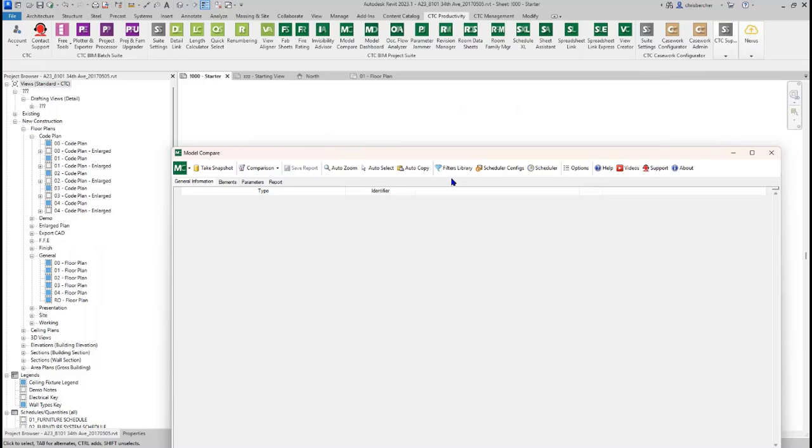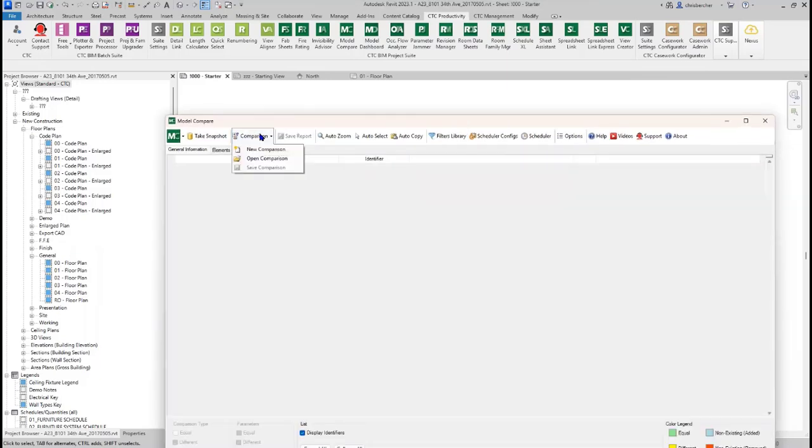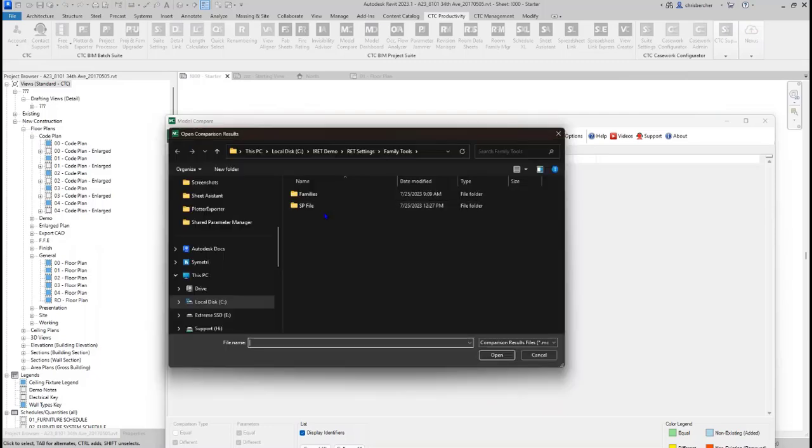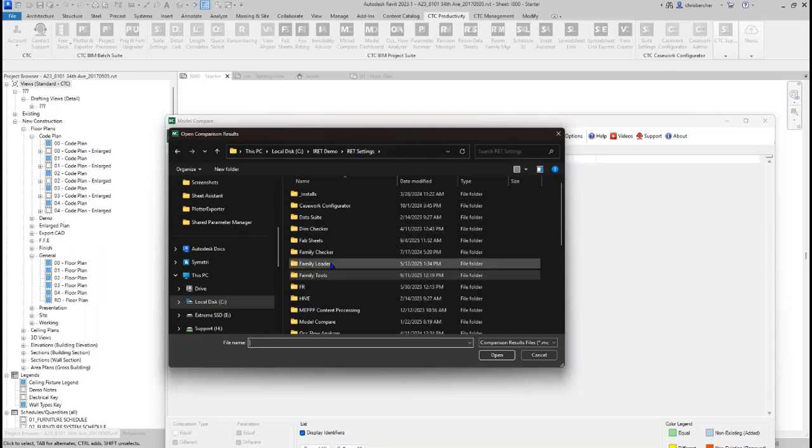This isn't as much a visual, like a PDF compare sort of thing. It's a spreadsheet style compare where you can look at a report that says, hey, this parameter, this family, this type, this position, this parameter is now different in this new version, or it hasn't changed at all, or it no longer exists because it got deleted, right?